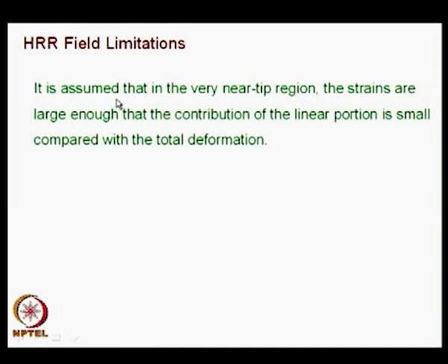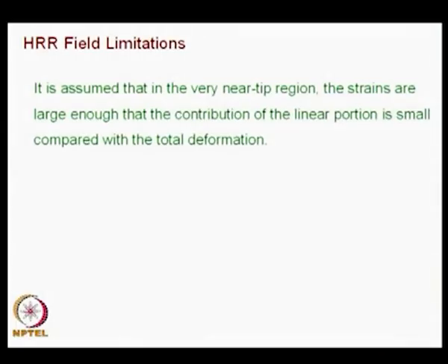It is assumed that in the very near tip region, the strains are large enough that the contribution of the linear portion is small compared with the total deformation. Such contradictions come in several fields. You will say something is large in comparison to something else, but that large quantity is still small compared to something else. Without such approximations, you can't perform any engineering analysis, but it is better to know that such approximations have been made in the development of the HRR field. That is what I am trying to point out.